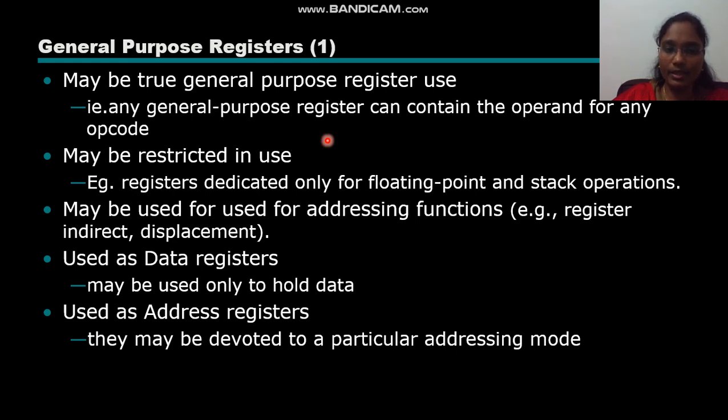or sometimes it can be restricted in use. Specifically it can be used only for a floating point operation, or only for stack operations, or only for addressing functions, like what we have discussed in the addressing modes, for indirect addressing or displacement addressing. So like that, we can have the general purpose registers either in a specialized way, or to use for any purpose. And the general purpose registers can also be used as the data registers or the address registers.